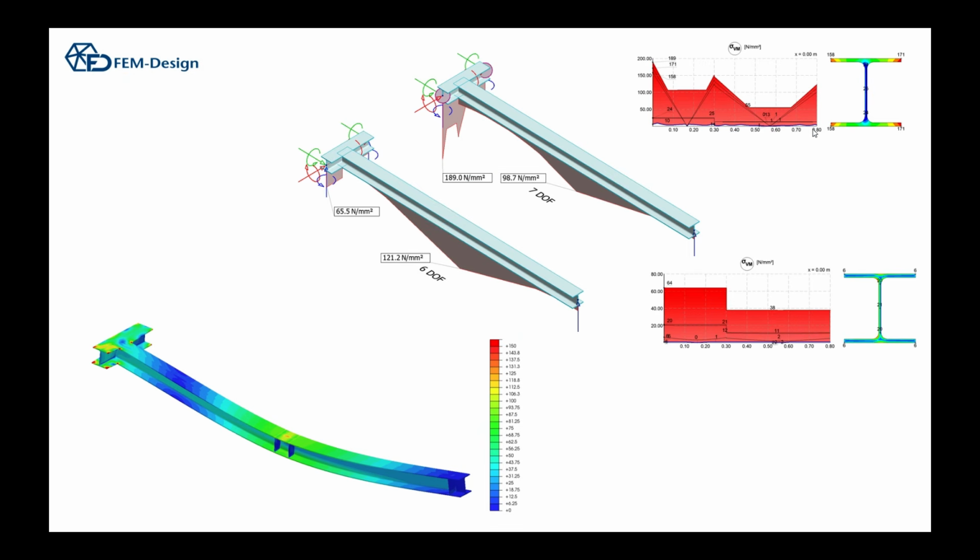If we look at the stresses of the same model, the classical beam model cannot predict these high flange stresses of the beam, but the 7 degree of freedom beam model, which is the above model, matches the solid model pretty closely, even with short spans, because we are using a general method here. The stresses are a bit off with the classical beam model.